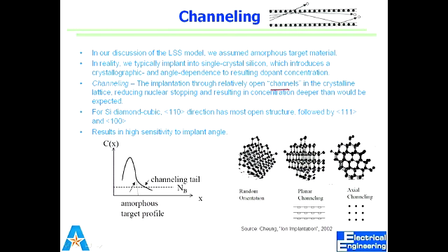With collision losing their energy. But in a very well-defined structure, some of them can zap through. And that is also a factor of the crystalline structure. If you have 110, it has many more open spaces than 111 and 100, right? So they would result in different channeling. So this would be different. What you call the channeling tail would be different for different orientations, right?